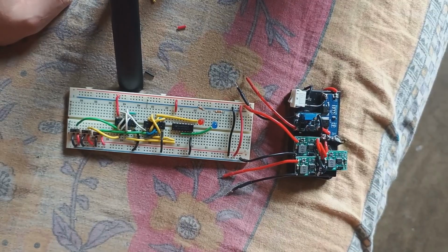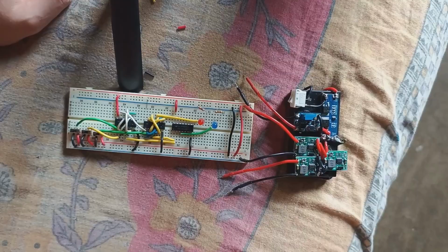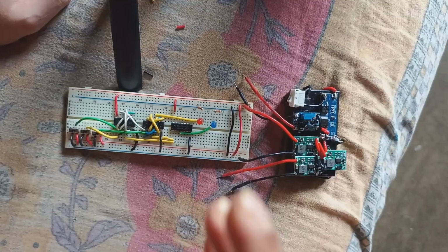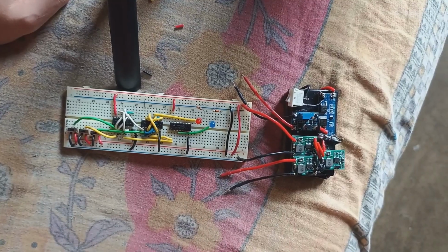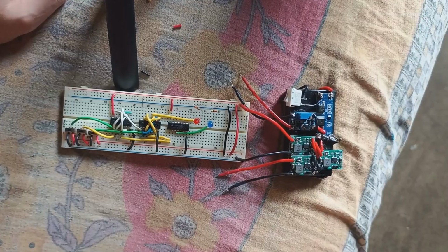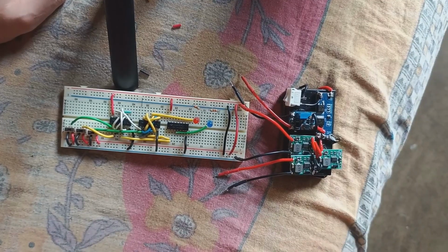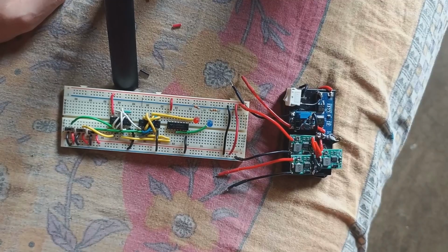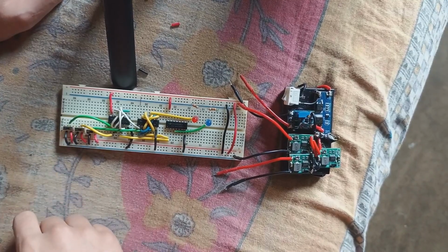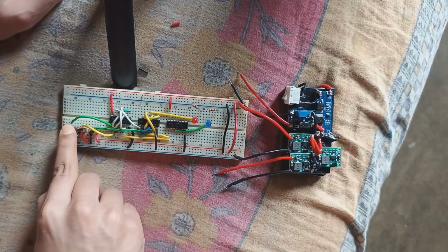For that reason, the LEDs were blinking very rapidly, which is completely undesired. We try to avoid that, as it may damage the ICs and the LEDs, because it is complete chaos. To get rid of that floating chaos, I have used slide switches, which look pretty, I guess.